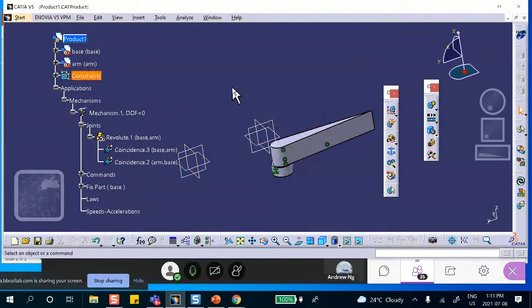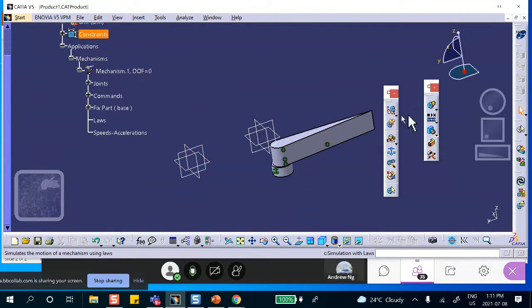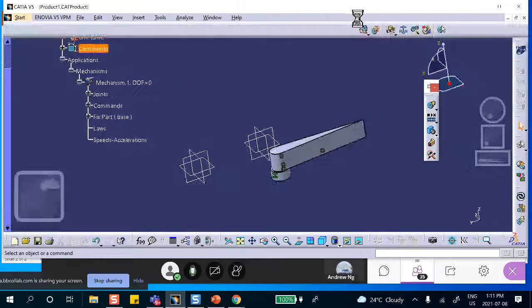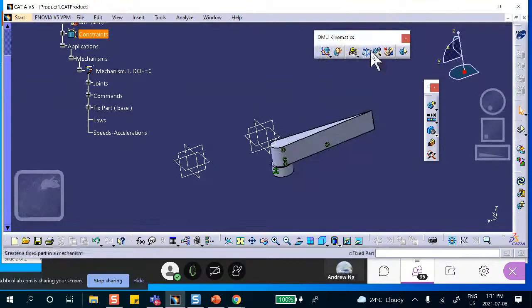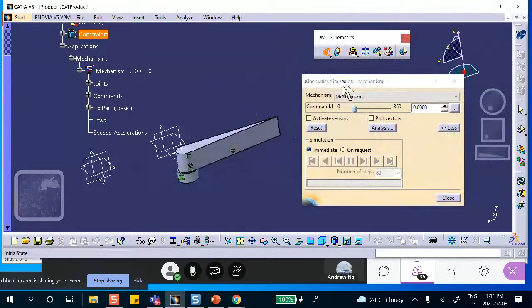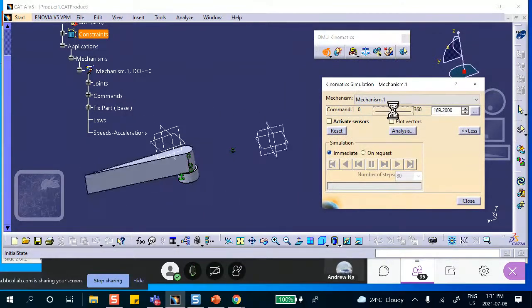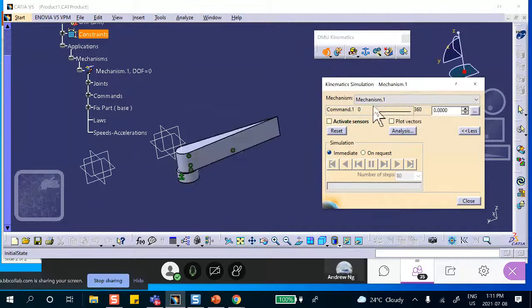Say okay. All right, how do I know if it's right? Or how do I know it works, actually? So you go to Simulation with Command right there. See that? This toolbar is extremely important. The one with the anchor, the one with the magic wand, the one with whatever I told you right now. Simulation with Command. Because this is a single degree of freedom, you're in charge, you're in command, you take the sliding bar and drag it. You see this? See? It's working.